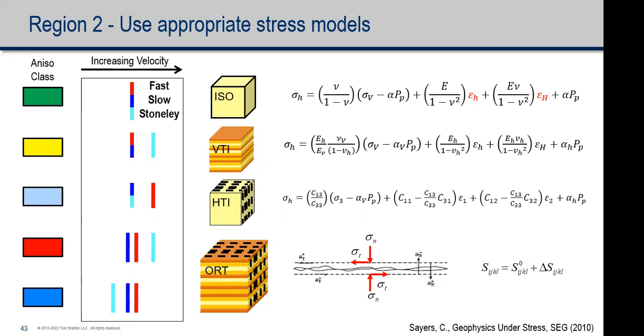We've got the issue of scale that I didn't really highlight here: your core data is typically from very small samples. And I love core data, I would take that, but for the mechanical behavior of, let's say, a geothermal project, where we're talking about a much larger scale than your core data, is the compliance of the rock at a larger scale the same thing as core?